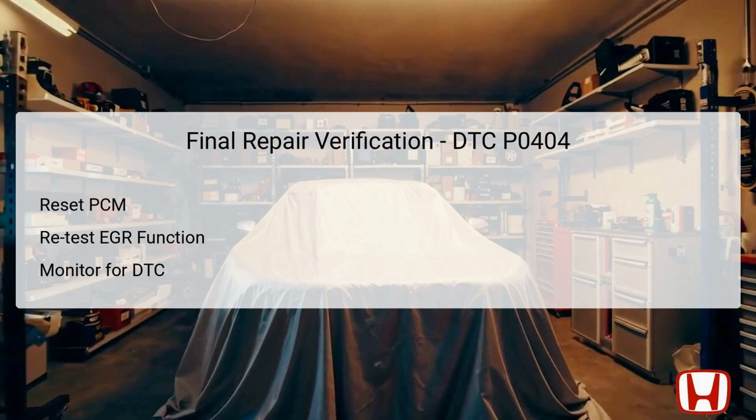After completing the necessary repairs or replacements, it is crucial to perform a final verification. Start by resetting the powertrain control module, PCM, to clear any stored DTCs. Then, restart the engine and hold the RPM at 3000 without load for a period until the radiator fan activates. After that, execute the HDS EGR test to confirm that the EGR function has returned to normal.